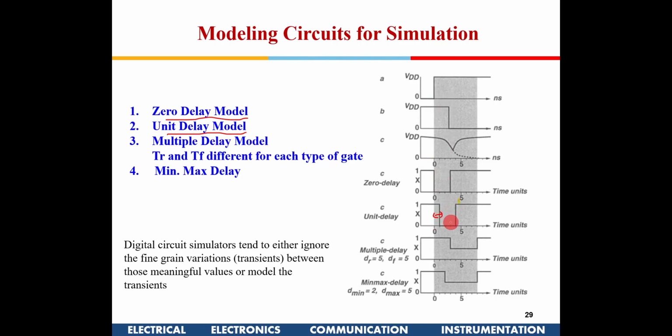In this particular case, if the input is switching and adequate time is not given, it is possible that when you do a simulation, it was trying to come here, and meanwhile the output has changed. So you can see all these kinds of errors coming up the moment you introduce multiple delays. You have to take care of that, and give adequate time for the signals to stabilize.